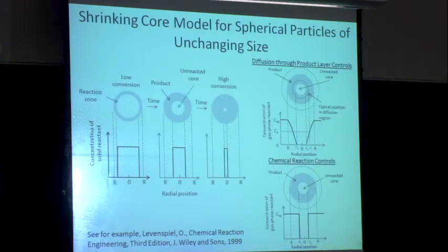And for the nanoparticle to oxidize, what it means is I've got to have the oxygen be able to diffuse across the oxide layer, or the aluminum to diffuse outward, and either have the reaction on the outer interface or on the inner interface. Typically, at higher temperatures, the oxygen's diffusing in, and so I have what looks like this shrinking core model where the reaction occurs at this interface and I consume the process.